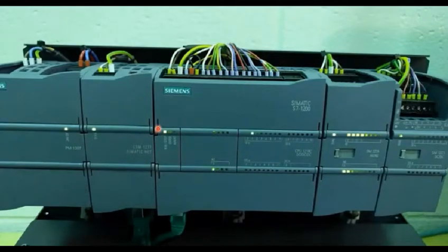And the next one is the Ethernet. For the net connection, you need to connect with the Ethernet, so you can use this CSM module 1277, SIMATIC NET. You can see on the upside, these cables are the power for these modules. One is the grounding, 2 is the power. If you want to connect your PLC with any other PLC through Ethernet, you need this module, SIMATIC NET, this CSM 1277. If you are going only for local, no need for this module.